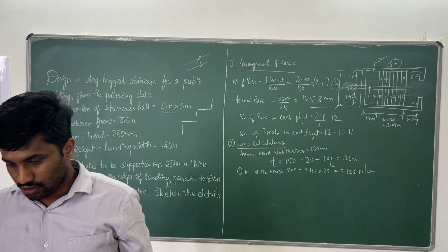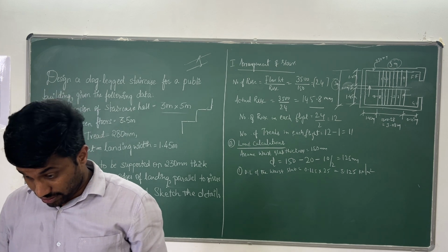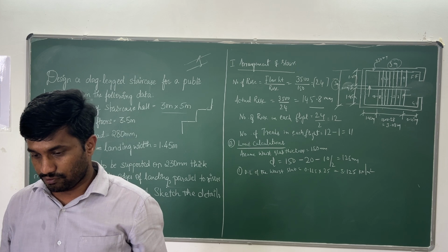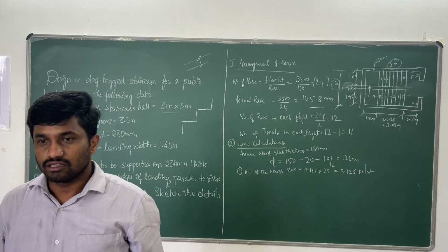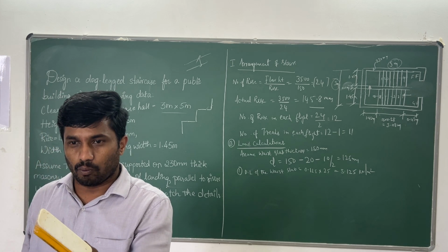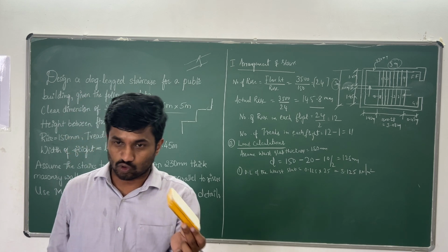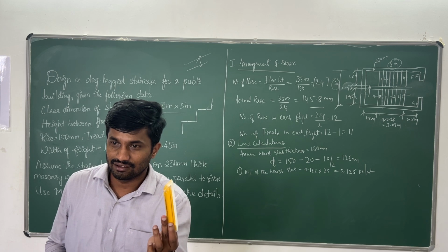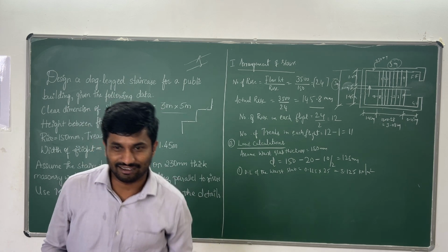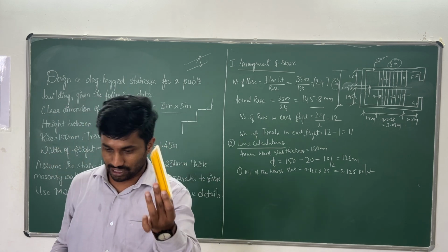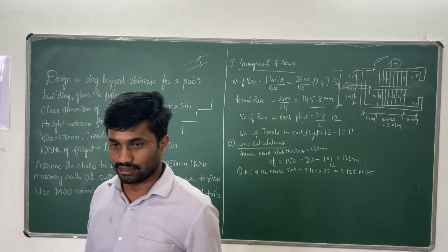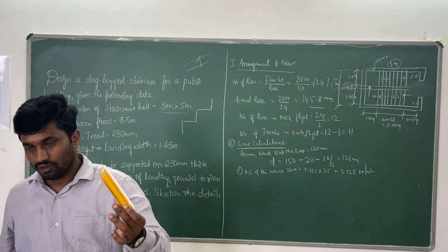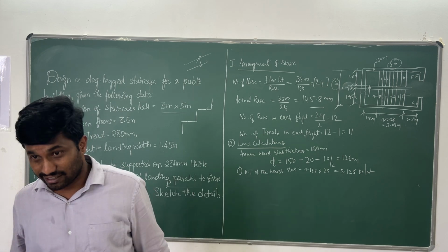Next, the second one, load. Here once again we have two cases. One is the waist slab slope. The waist slab is generally sloped. In the slope we have both the horizontal direction as well as the steps, one vertical, one horizontal. So this is the dead load of the slab on slope, but the landing is horizontal, which is another one.